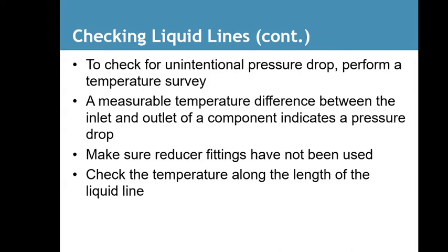Check liquid lines, continued. To check for unintentional pressure drops, perform a temperature survey. A measurable temperature difference between the inlet and the outlet of a component indicates a pressure drop. Make sure reducers and fittings have not been used. Check the temperature along the length of the line.